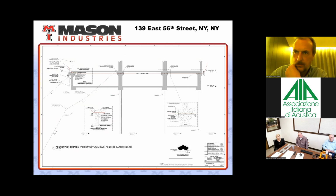We would prefer to be above on the column capital at the first level before the second floor. And then we can isolate and not even have to think about the requirements for not having short circuits through the soil. So the isolation plane is a critical term for establishing the bearing location so that you're in a position where you're not compromising the acoustical integrity of the structure. It's a critical discussion with the architects and the engineers.